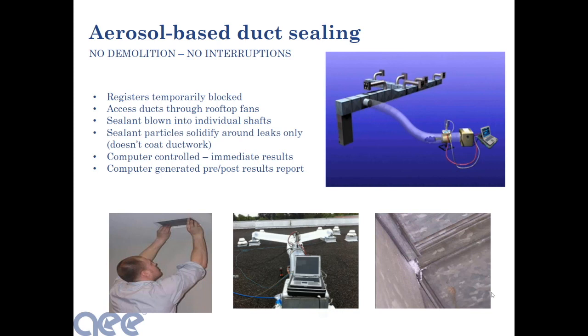And the idea was that they were going to use aerosol as a way to seal up ductwork and avoid all of the negatives that we had traditionally associated with duct sealing. I'm just going to take a minute and explain to you how aerosol duct sealing works. The vision was the contractor would come into the building without pulling down the ceiling tiles. They would simply go to all of the vents and block the vents. Then they would block the air handler. Now there was nowhere for the air to go but through the holes. Then they would connect a fan to the duct system, and that would push air through the holes.